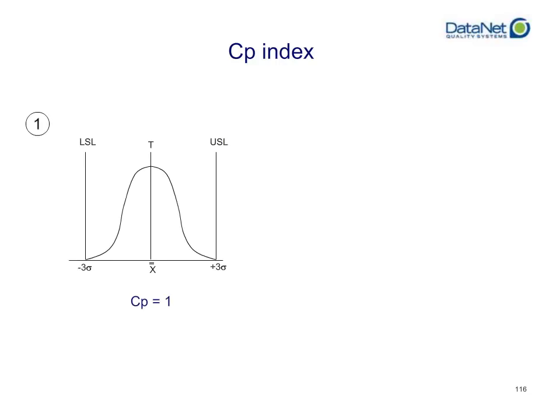If your CP equals 1.0000, that means that in an ideal world where you were producing most of your product right on your center line, 99.73% of your data would fall within specifications, within plus or minus 3 standard deviations from your center line.